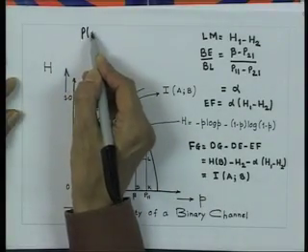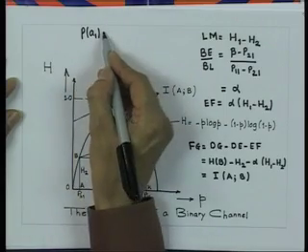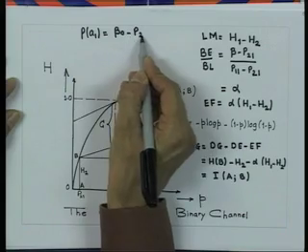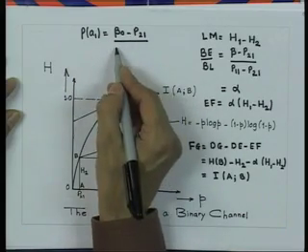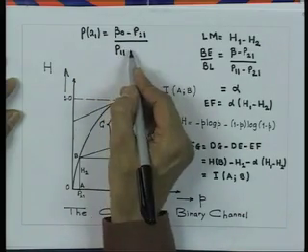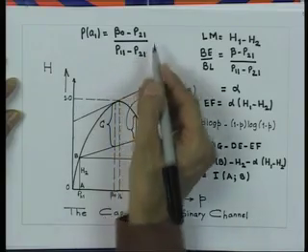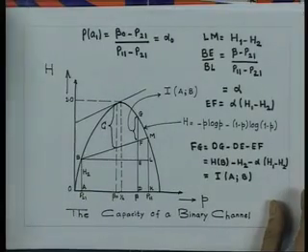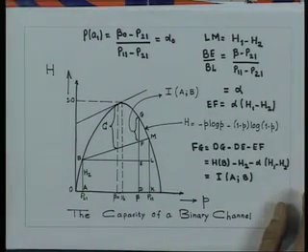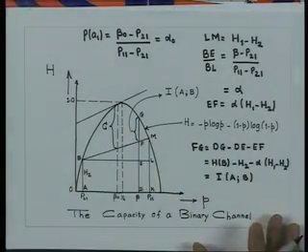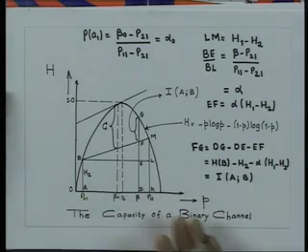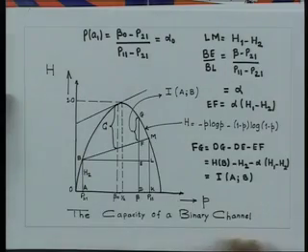probability of A1 is equal to (beta naught minus P21) upon (P11 minus P21), which is equal to alpha naught. So, this will be a general procedure to calculate the capacity of a binary channel based on a graphical approach.